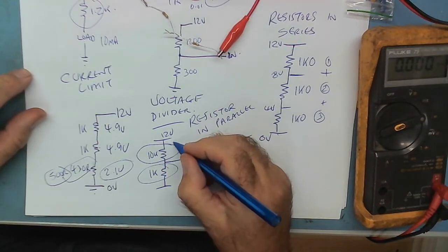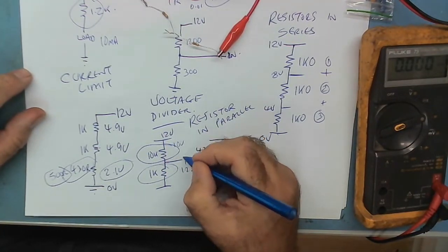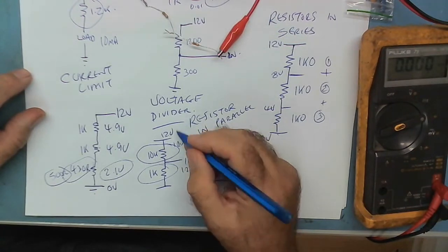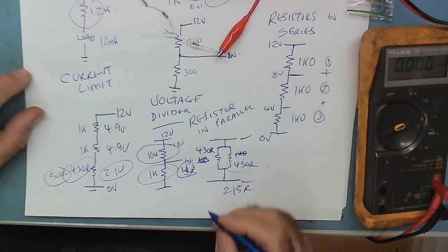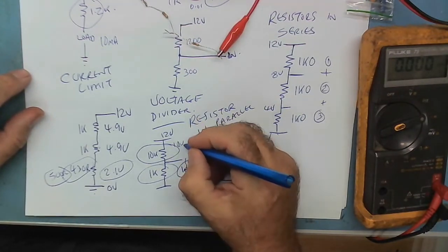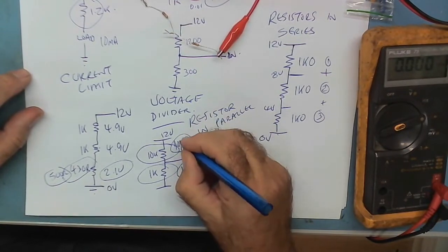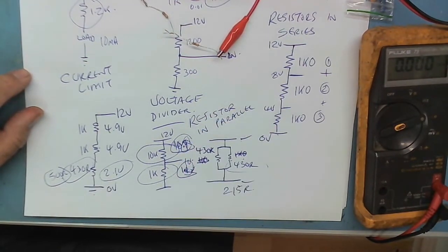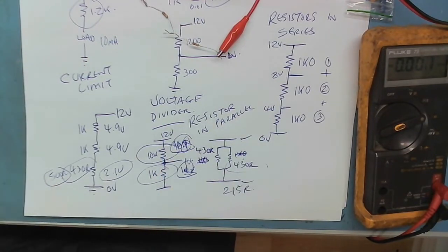There's going to be 10 there, doesn't quite add up. So you say, well, that must be about 1.2, and this must be 12 then. So it's probably something like 1.1 volts here, and then 10.9 here. I don't know if those are correct, but you get a good idea of what it would be. You know full well the voltage there is about a tenth of that.